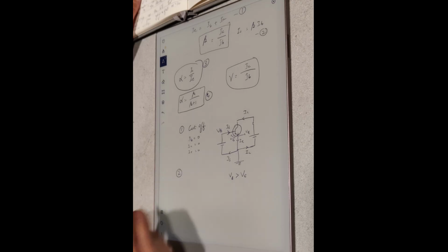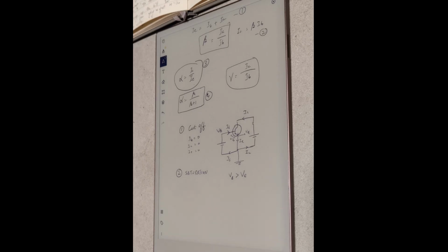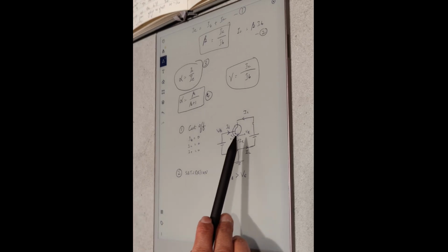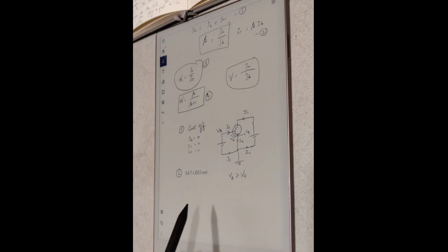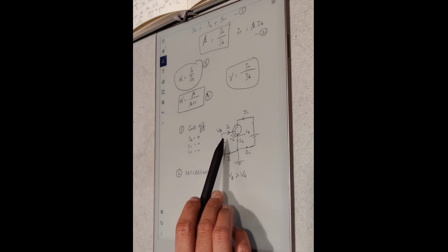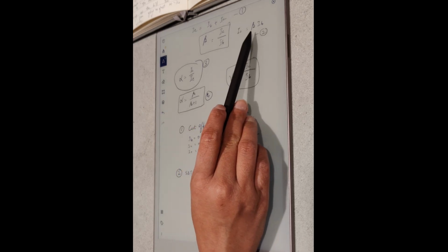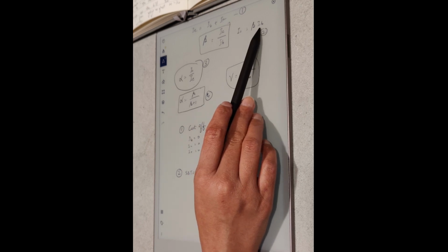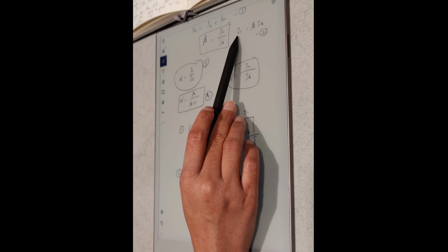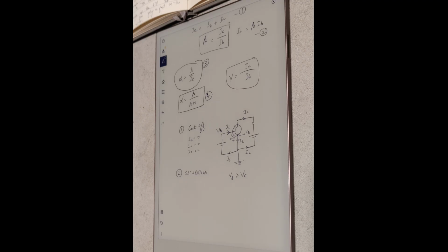Then the second mode is called saturation. Saturation is the opposite end. Saturation is when the current that can flow in the circuit, especially this IC, has maximized. So even though you keep increasing IB, there's going to be a point when IC no longer increases. Remember this equation that we derived, that IC is equal to beta times IB. It means if you increase IB, you're also going to increase IC with this proportionality. Now, why does this saturation happen?